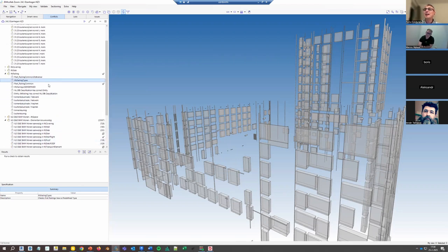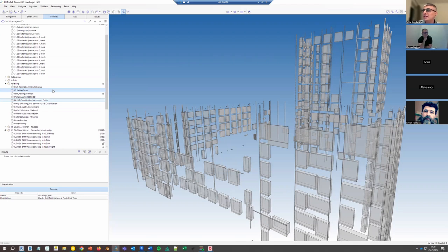Okay, I'm done. One more question, Menno, because we are still here. Let's answer this question. Engelbertus is asking us: using the latest Revit and IFC export version delivered when installing Revit, some things don't get exported correctly. Some parameters just don't get exported, and also some shafts don't get exported. Both are said to be bugs, but they have been in there for a long time. Some geometry stuff like the shafts does not get exported using IFC4, but a lot of companies specify IFC2x3. I have a full rant on this as well, but I'll let you, Menno, answer.